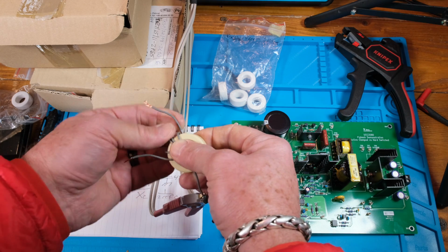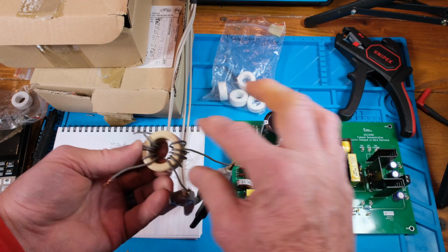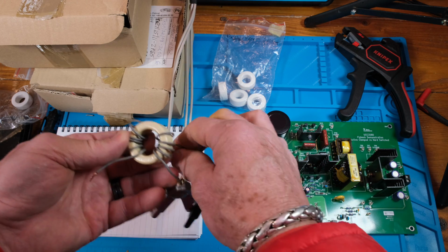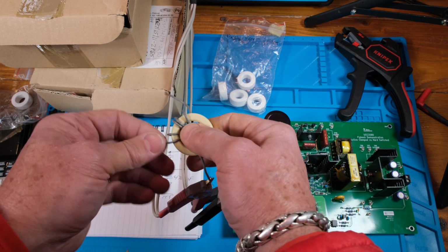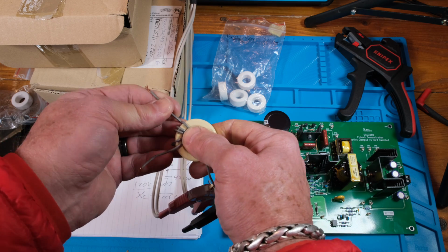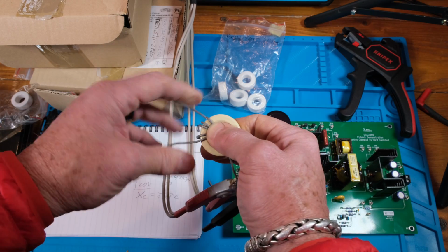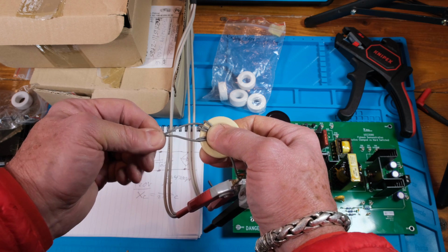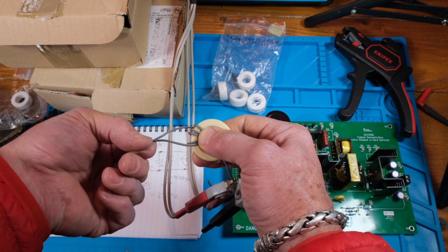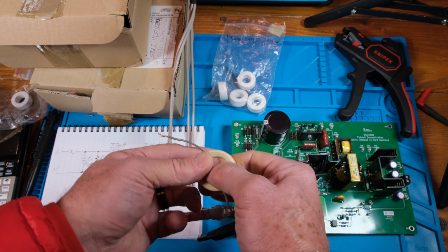So the reason it doesn't completely short out the core is because of the leakage inductance. Well, one thing you can tell, I don't have them wound tight, so they're not coupled as good as they could be, but they're never going to be coupled perfectly. So that leakage inductance is actually your differential inductance, okay? So I'm down around 3.4. I've put it a little bit tighter, and when I short them, I get about 3.4 microhenries.